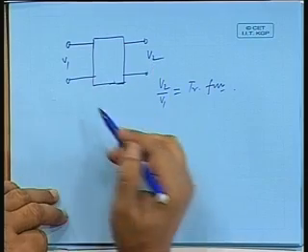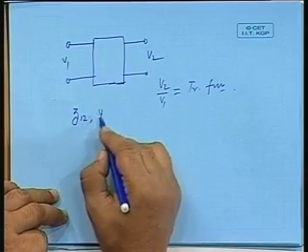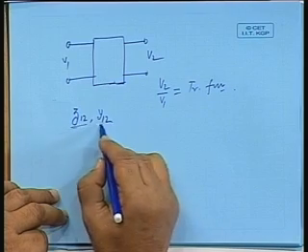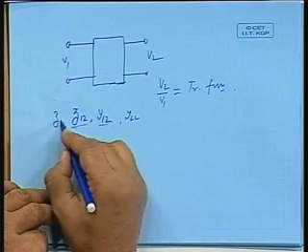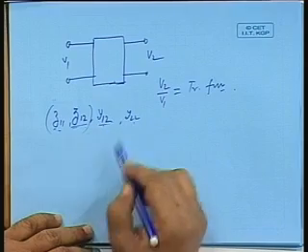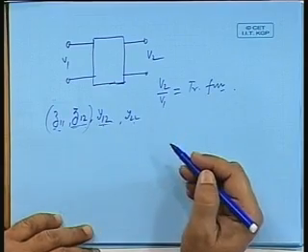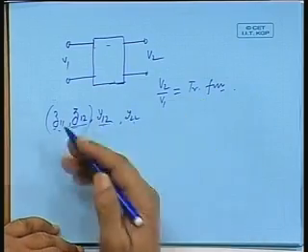Let us write Y(s) as V2 by I1 or I1 by V2, I1 by I2 and so on. That means, you may be given the specifications either in terms of Z12, Y12, Y22 and so on, and Z11. So, specifications can be given in terms of Z11, Z12 or Y12, Y22 or V2 by V1 and so on. You have to determine a possible network. So far we have studied the driving point synthesis. Now, we shall be going for 2 port synthesis with transfer impedances.